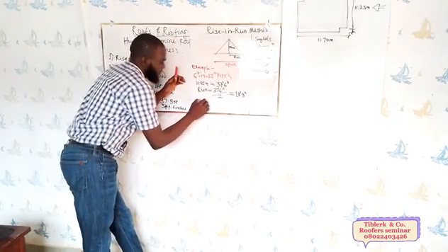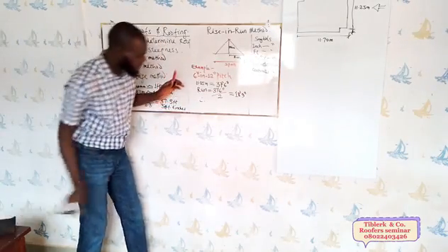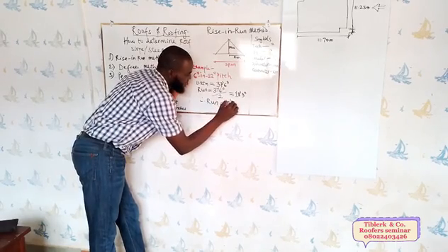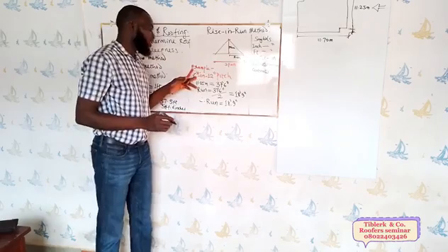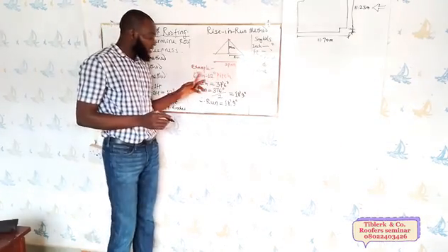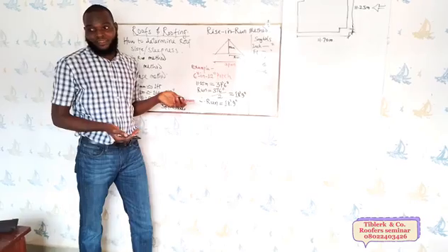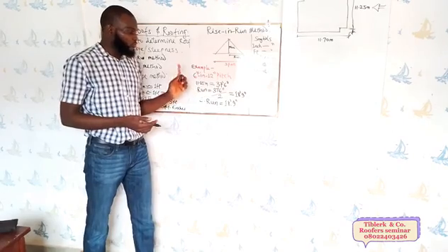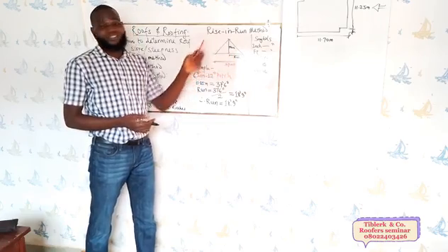Therefore, our run will now be 18 feet 9 inches. Now, the specification says our pitch is 6 to 12. So this can be reduced further by saying what ratio they are. That will make it easier, in ratio 1 to 2, and the 2 is going with the run. So it means half of the run is what we need as our rise.